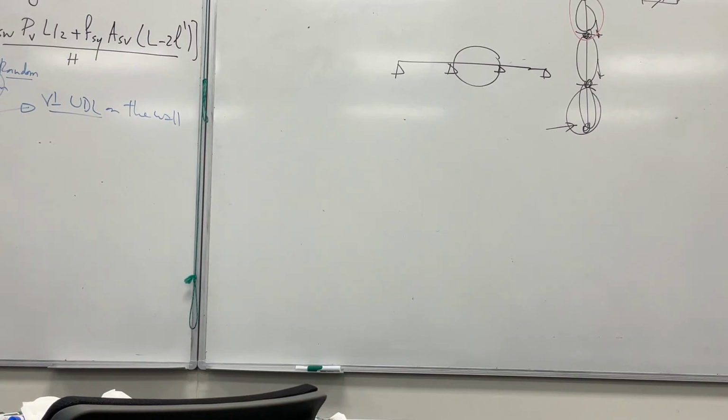After we know PV, now we need to decide if it is a uniform load or a distributed load. Can you read the definition? Do you have the standard with you? I didn't bring it. Can you read the definition of PV for me? The applied uniform vertical load. So it should be uniform. We'll try both, just to refer back to the example, but the definition mentions it is a uniform load.